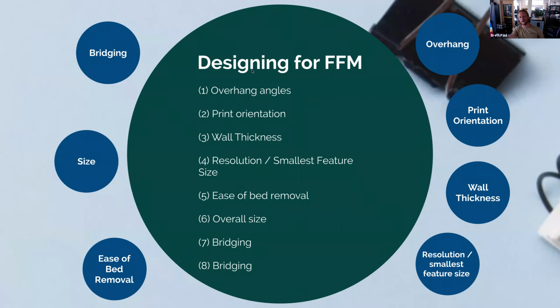This is a more general note for 3D printing on designing for manufacturing, and that is 3D printing is really useful when it comes to prototyping a design. 3D printing is not great for scaling a product. If you're trying to make hundreds of the same thing, 3D printing is pretty darn slow. And that's something to think about also as a concept of DFM, is choosing the right process for what you're making. So if you're looking for rapid prototyping or just getting a first order estimate for how something will fit together or how it looks, 3D printing is great.